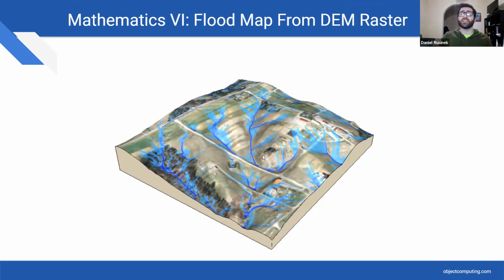And then just another cool use case, and there's a ton of them, but I thought this was a cool one. Since we know the elevation, and we know that water is going to go in the path of least resistance, we can calculate and create maps of where water is going to drain. We can simulate a certain amount of water pooling in certain areas. That is another use case that railroads are very interested in, because they can try to figure out where there might be pooling in the ballast that might cause some kind of structural damage underneath, because the LIDAR can't really see underneath any of the ballast or the ties, but we can see the surface. And if we know there's pooling, then there's a good chance that there could be some damage underneath.